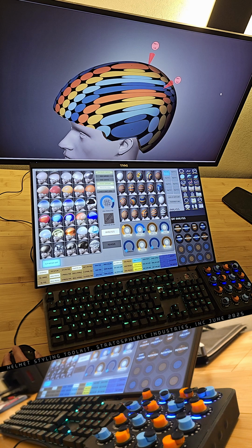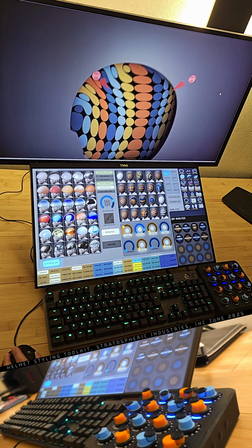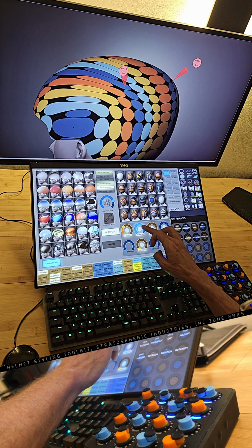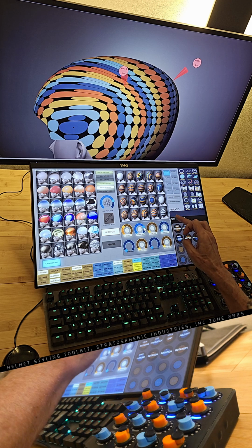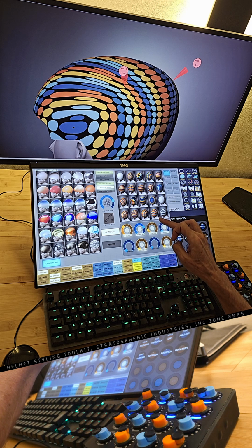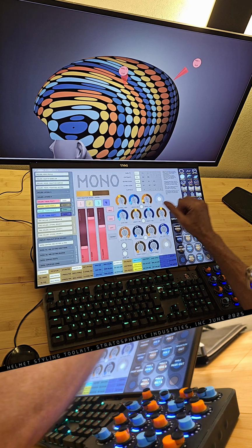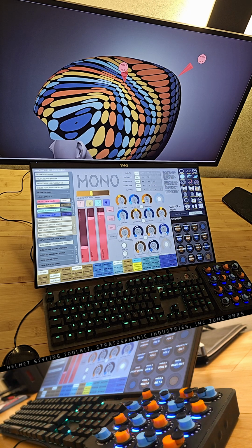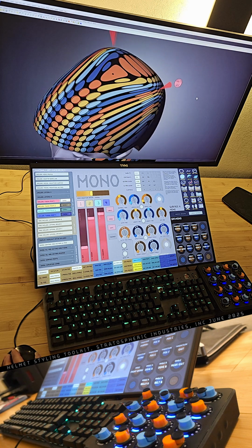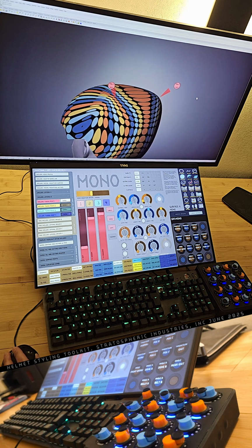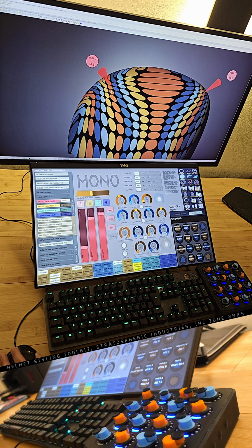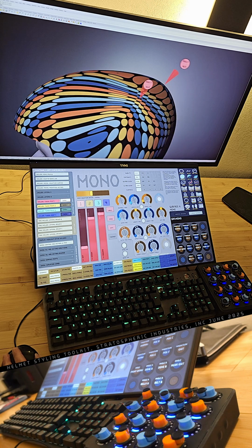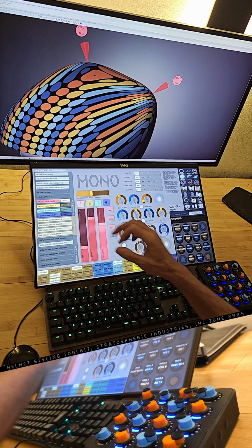Analysis. We can watch the effect of tweaking that point in real time. Let's just watch the analysis here. Change the element size a little bit smaller, a little bit higher resolution, a little bit bigger gap just for the sake of watching it, and go back to mono surface. Tweak point 1 is active. A massive change. And we see very clearly the effect on the analysis surface. Curvature dots are getting much smaller. Curvature dots are getting much bigger here, indicating much more flatness to the surface. Let's dial those back down.